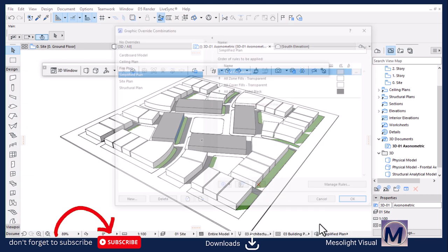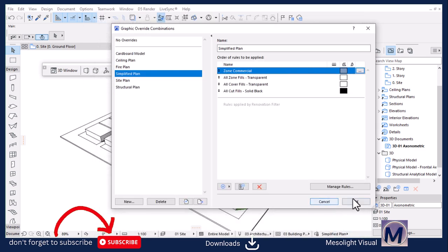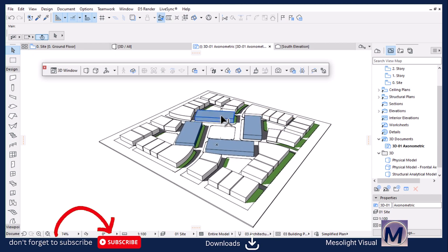We go back again to the graphic override combination. What we need to do here is edit this. Go back to edit rule for zone commercial. What we've missed is the color for both the overrides fields. You see, we only covered the cut fields, but for the cover fields we didn't do that, and for the drafting fields we didn't do that. If you select the cover field, watch and see, boom, it affected. So that's how you use graphic override combinations to filter and create variation of graphic styles.